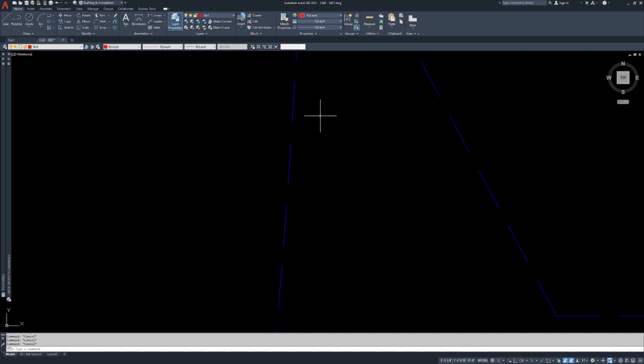So if we were to go into the line type file right now, line types are designed in that way, where you tell it the distance of the space, then you tell it the distance of the line, because it's all based on that old system. Pen down, pen up. If the pen is down, it's moving this distance. The pen comes up, it's moving this distance, which gives you gaps and actual line work.